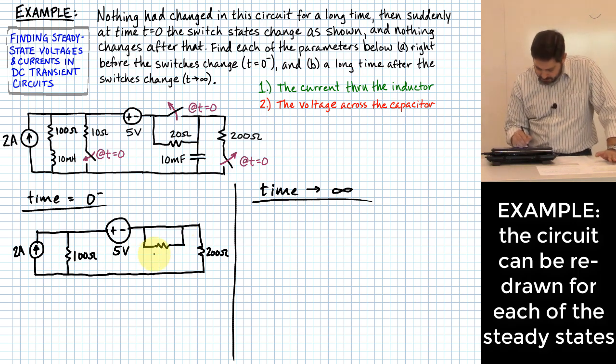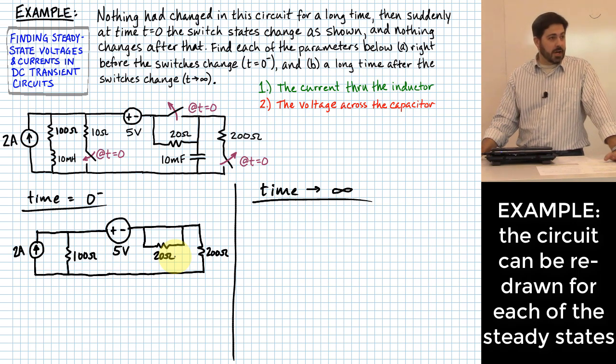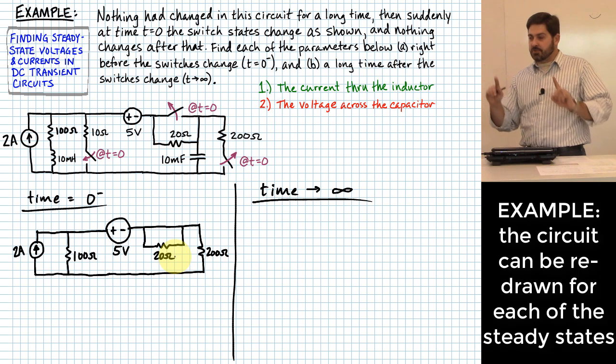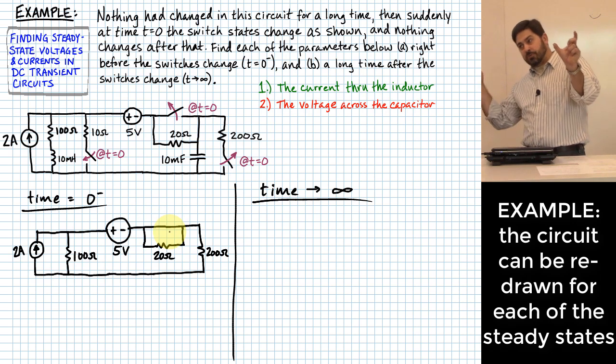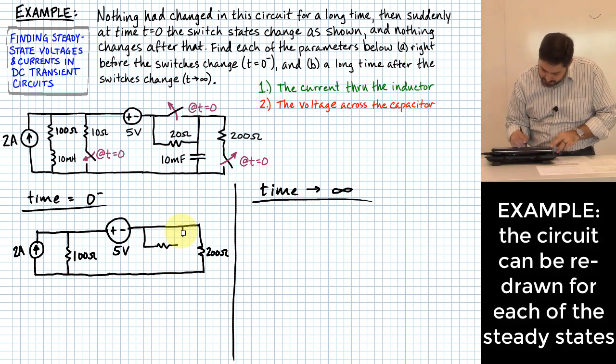Now, I could write the 20 ohm on there if I wanted, but many of you are looking at that going, would that even do anything? Some of you say, nope, that doesn't look like it would do anything. Why not? That's a short circuit, right? The two ends of that resistor are connected to the same node. And because they're connected to the same node, that's essentially 0 resistance for that path on the upper side of it. And if there's a 0 resistance path, how much current will flow on the path that is non-zero resistance? None, right? So since no current will flow on the 20 ohm resistor in that case, we can eliminate it.